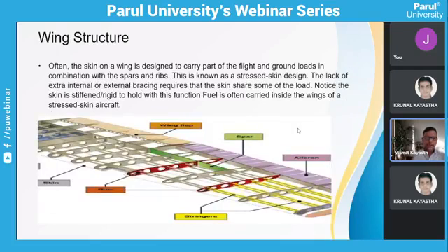Okay, so moving ahead, I would like to go ahead with the structure. We all know what a wing is made up of as of now. Mostly the things that are covered here are spars, that is the horizontal load balancer or takers. Vertical load balancing is taken by the ribs. Altogether, they form a wing, and the stringers are also there to strengthen the trailing edge and the backside of the wing. We are also using ailerons, but we are not considering them in the wing structure as of now, because they are a different component which takes the wing to a lift position.